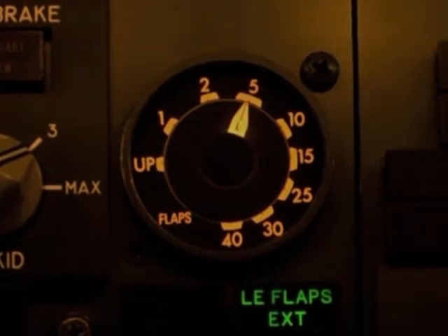For example, they have a higher speed, and in order to reduce the speed, they extend the flaps. This way we damage the drive mechanism of the flaps, and we bring more stress on the flap drive mechanism, which will be very costly for the company to pay for the repairs. Flaps are only there to help us have more lift on the wings. They are not speed brakes. They are not panels that help the pilot to reduce the speed. So this common mistake should always be avoided, and we should always keep in mind what the usage of the flaps is during the flight.